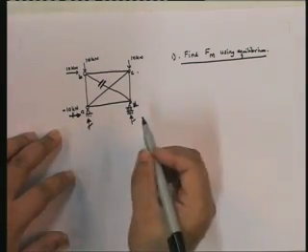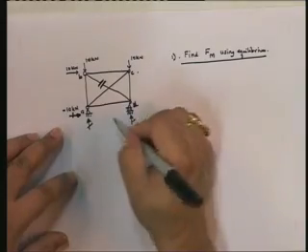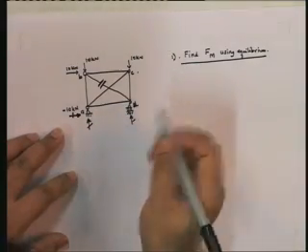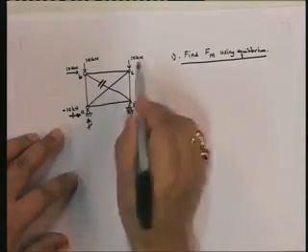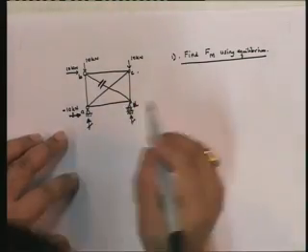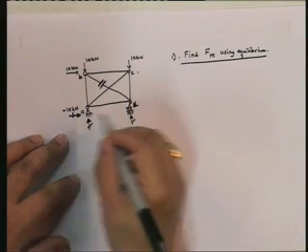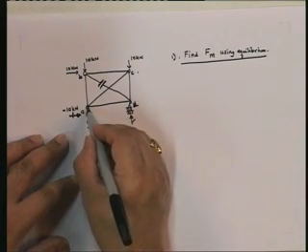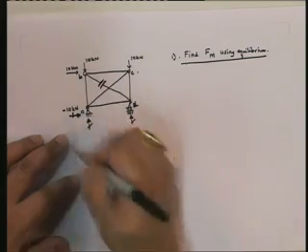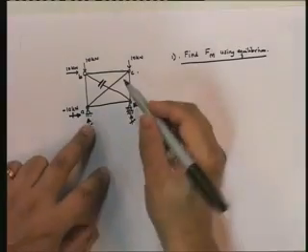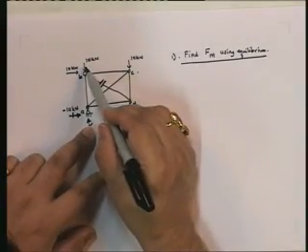Now sigma Fy equal to 0 gives me what? That this plus this is equal to 20. We know that. However, that still does not help us. So what I'm going to do is take moments about point A of all the forces, and from that I can find out this value. Let's look at what the forces are. This does not have any moment.